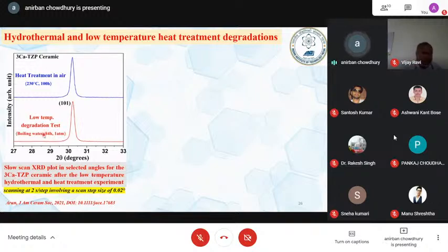You put the sintered target completely immersed in boiling water, and then run a slow scan. You don't do any grinding or polishing, just soak it with a tissue paper and run the XRD immediately. Even at a slow scan like this, 2 seconds per step with a step size of 0.02, do you see any monoclinic phase? No, we don't.